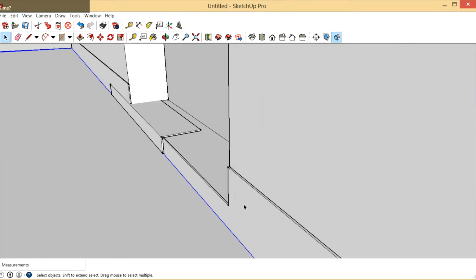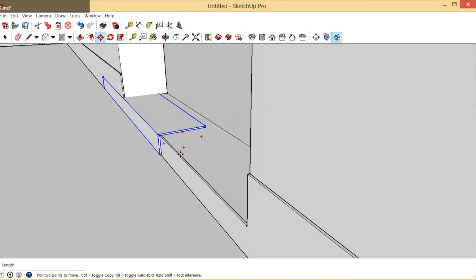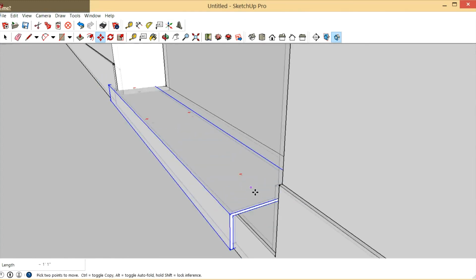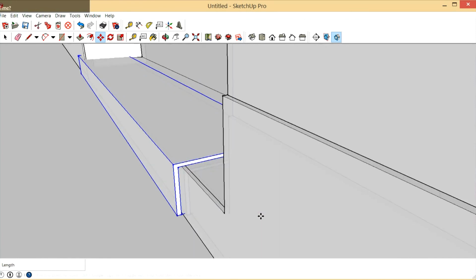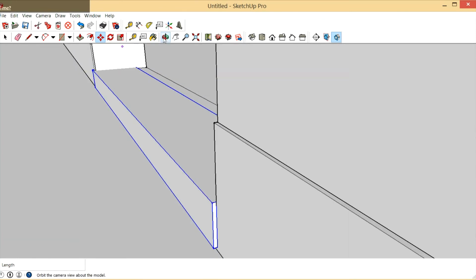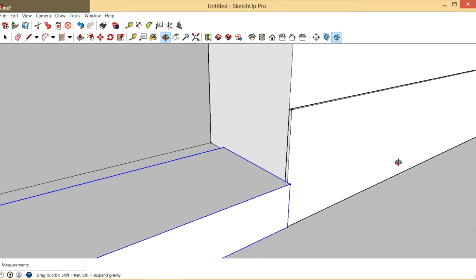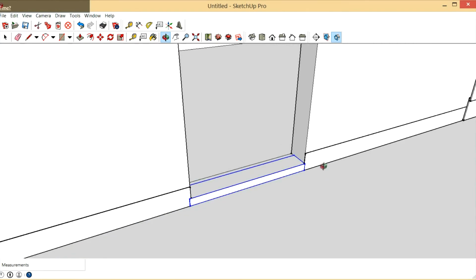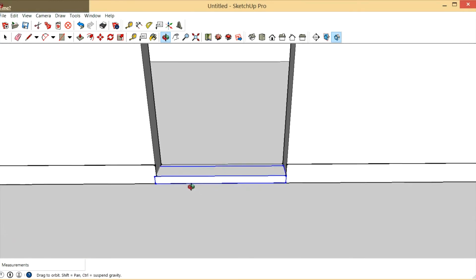that piece of flashing. Now if you can't do this, if you can't get this piece of flashing in, or you don't think it's practical for you, it's fine. I'm just showing you how we do it at Artisan Construction. And then we would seal this again. So if water wants to back up under your door, you've got very good positive flashing there.